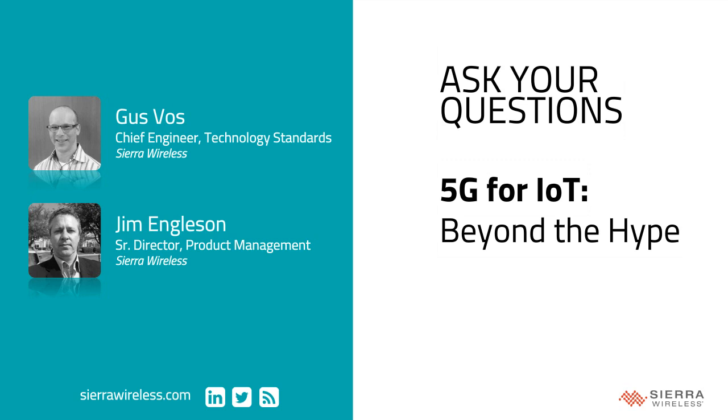The unlicensed spectrum. Of course, the benefit is, well, it's free, right? People can use it within the rules that the regulator body has set up. Often those rules can be a little bit difficult, like, for example, transmission times. Especially in the 900 meg band, you can sometimes only transmit 1% of the time. So you can't often utilize the spectrum in the same way.